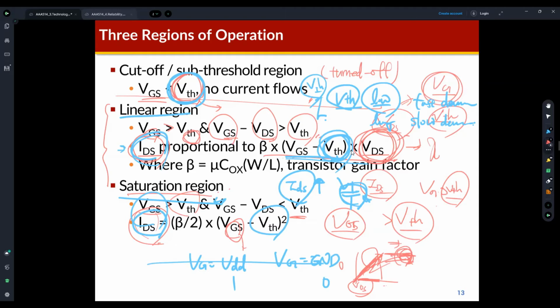Actually, this threshold voltage level is determined by the semiconductor node, which means the channel length and channel width of the MOS transistor. If we can make smaller devices, that means the technology node is advanced, so the channel length is shrunk.